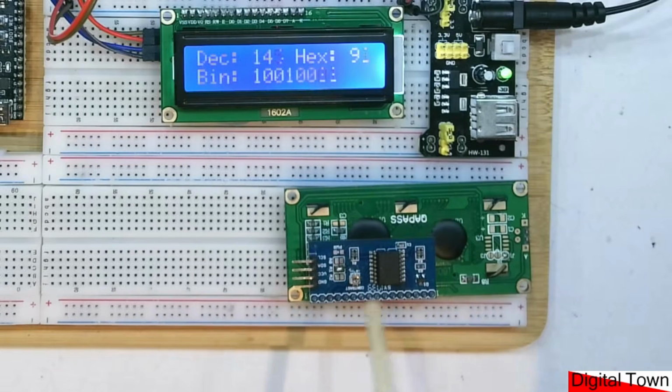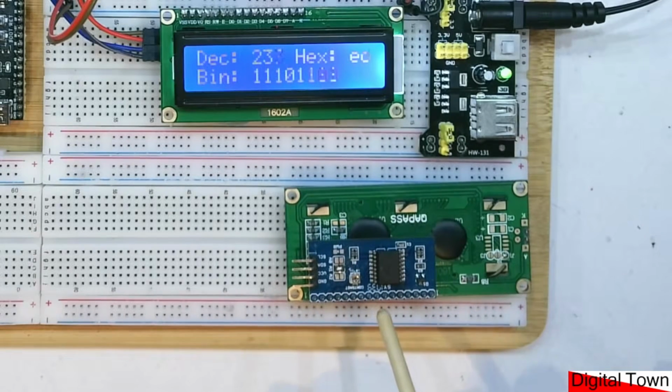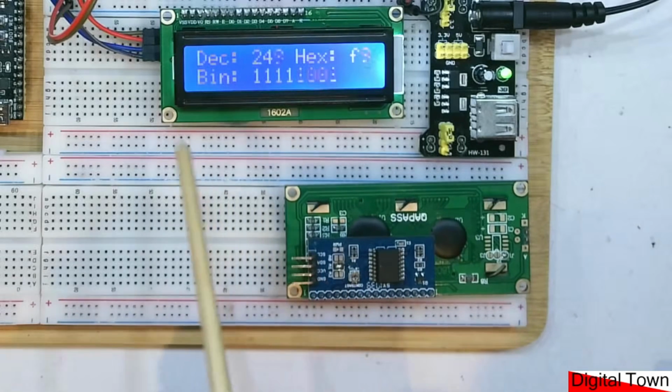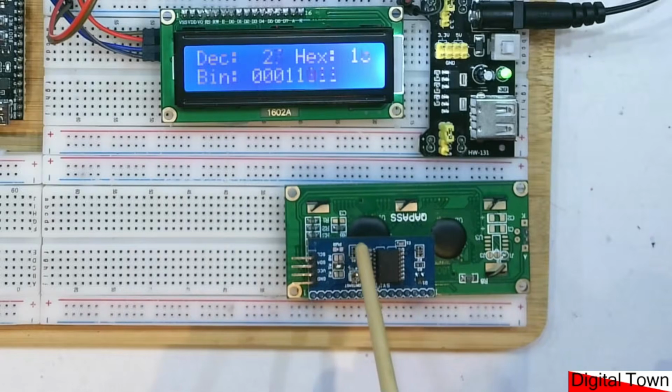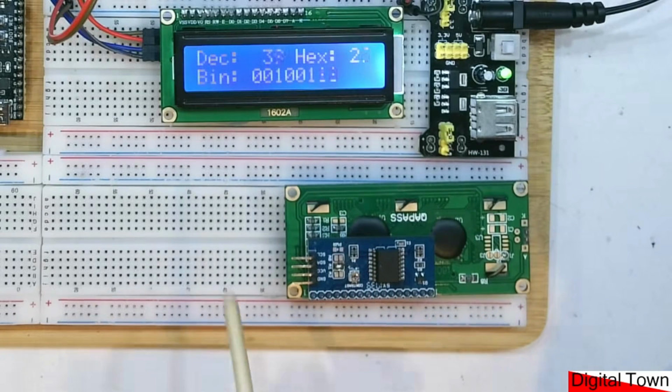Now by default, I think from what I can remember, they have a hex value of 27 by default. But you will see here that I have soldered over the little connector between A1. So you've got A0, A1 and A2. And by putting solder blobs over these, you can change the address of the board. Now the reason I've changed the address of this board and this board is it comes from a bigger project where I had 4 of these screens running together. So each screen needs a separate address. So the first thing I need to do is find the address of this particular board.